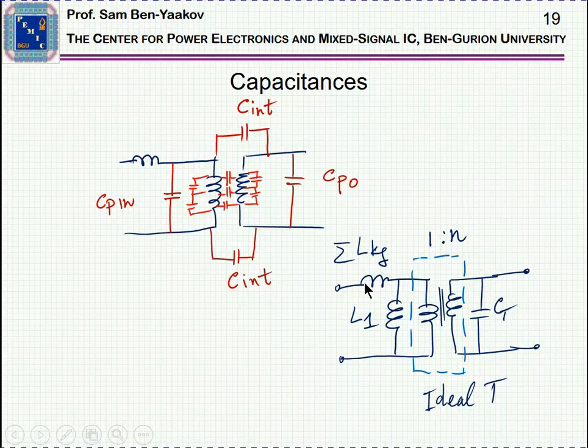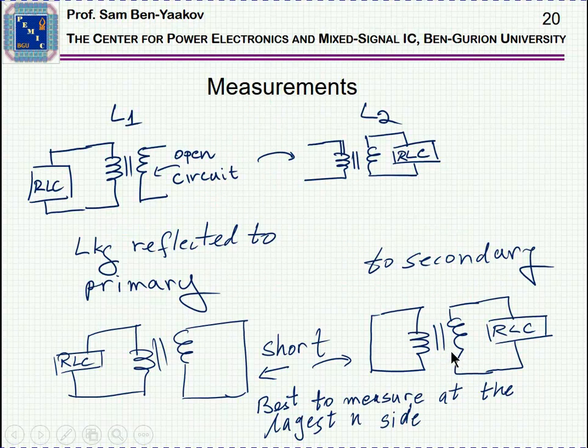We have the leakage, which here is reflected to the primary, the primary inductance, the ideal transformer, which is represented in one way or the other, and the parallel capacitor. Note that the inductances of this ideal transformer are not supposed to interact with the circuit. This is just a conversion action, which you can, of course, emulate by dependent sources, as I've shown before.